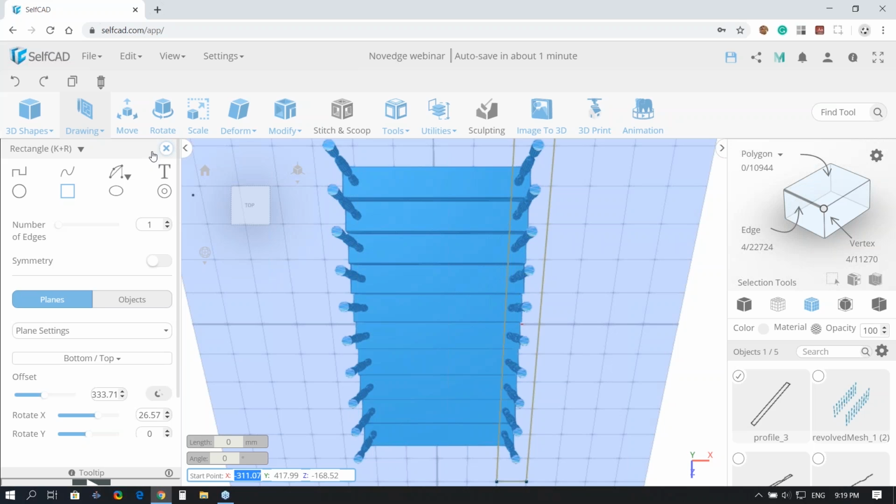But before I do so, I'm going to add a fillet to it. I'm going to add some details. Let's say I'll make it 5 and add the number over here, 5. And as you can see, it added nicely, it rounded nicely. All of these tools are reusable, so you can actually make a fillet or chamfer on the profile as well. But I think the polygon structure would be better if you first make it on the mesh. So yeah, that's why I did it this way.